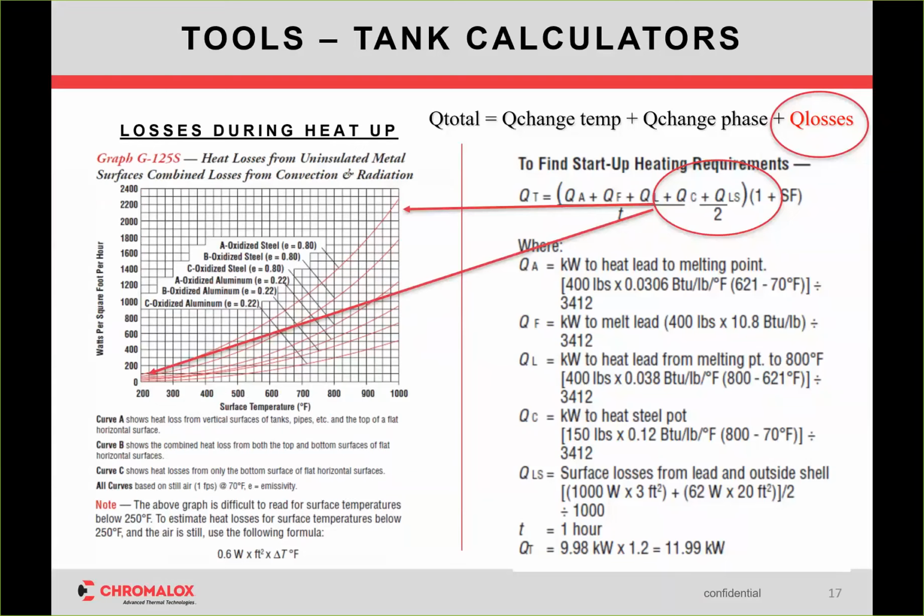because it can make a difference over time of how you size your heater, what you decide on, and a lot of times you can decide on a smaller heater. As long as you're overcoming your losses at the maintain temp, that's all you're trying to do. You're already at temperature. But everything above that is the input to get it to temperature, and that's what you have to consider. And that's based over time. Hope that makes sense to everyone. That's kind of a wordy way of explaining it, I should say.